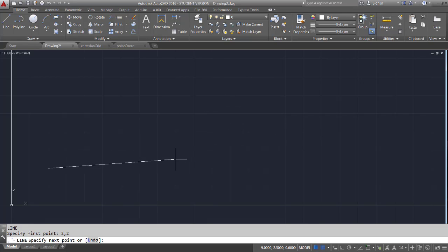And I can do it at any angle, but it's hard to understand what's happening if you want to draw a line accurately and give an accurate distance. But the snap mode does allow you to understand the increment that you're moving along. And one way we can control that is if we go down here to the drawing coordinates and right click on that, and you'll see that right now it's set to absolute. If we turn on relative,